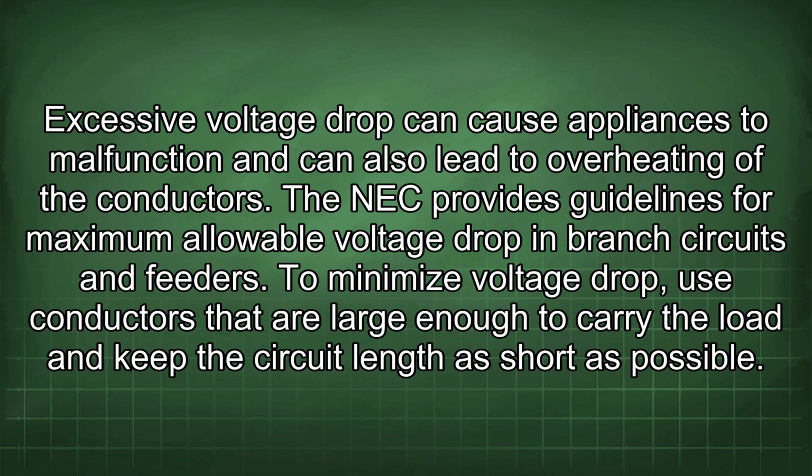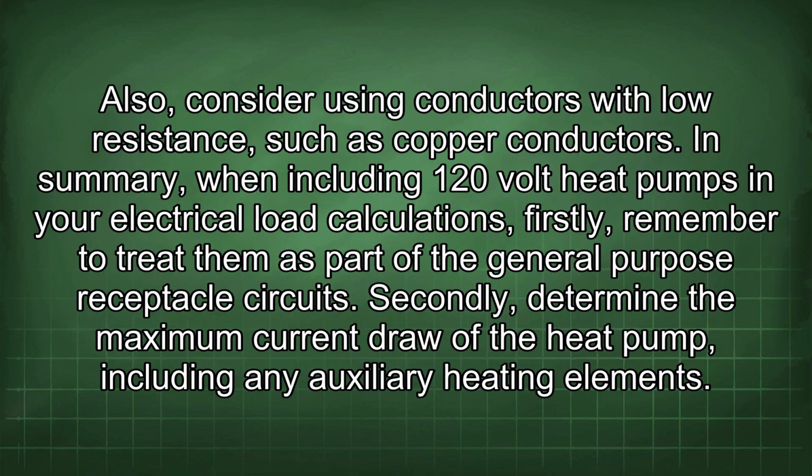To minimize voltage drop, use conductors that are large enough to carry the load and keep the circuit length as short as possible. Also, consider using conductors with low resistance, such as copper conductors.